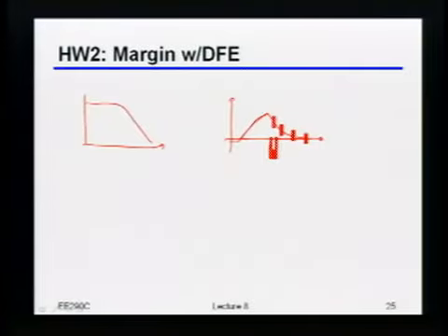Then all of the following taps would also be canceled, because they were all just scaled copies of that same value. This worked particularly nicely on the transmitter. Then I also asked, what happens if you actually use the DFE? So instead of doing some FIR filter at the transmitter, you used a DFE for one tap to kill the immediate post-cursor, right?